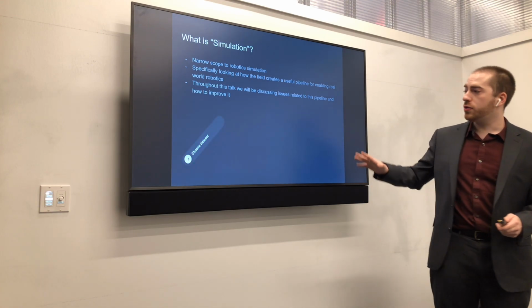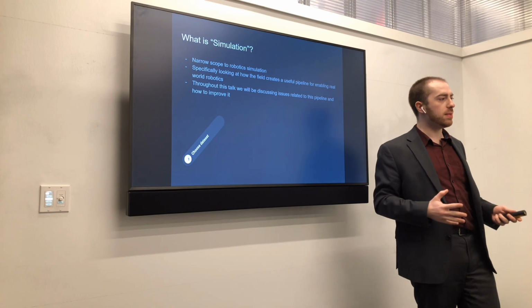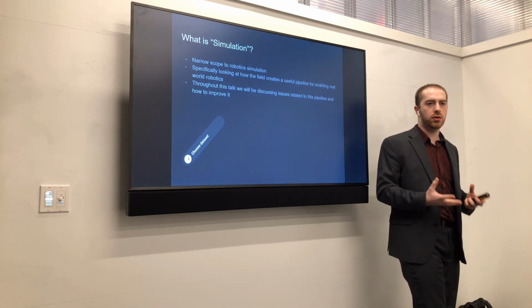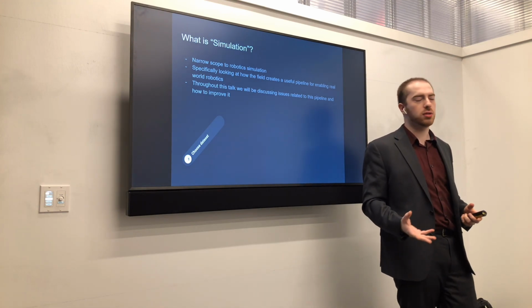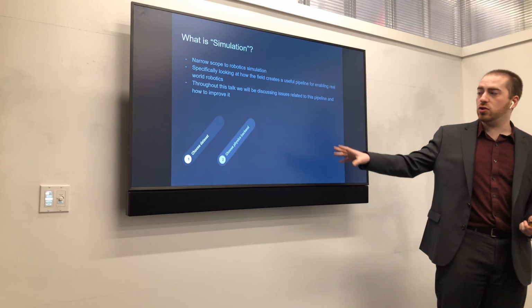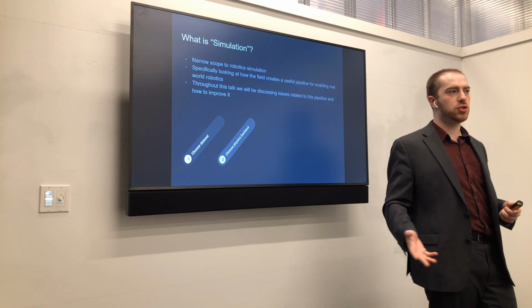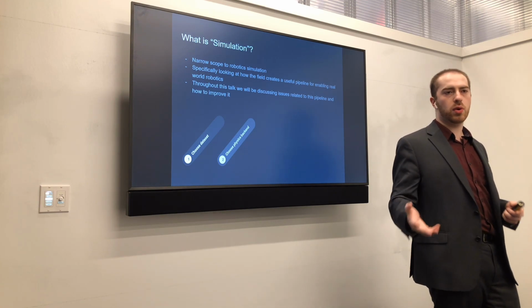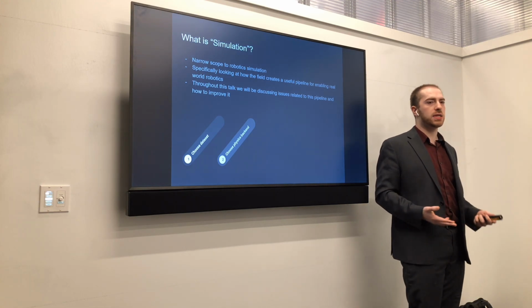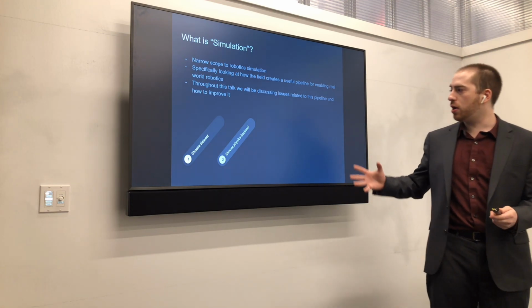general problems. So first, when you're considering a robotics sim to real problem, you always want to choose your dataset. What is the ground truth data that you're going to use for training an agent, for verifying that your application works correctly? Then you choose a physics backend that supports the particular problem you're trying to solve, whether this is MuJoCo, whether this is Habitat Sim, whether this is AirSim if you're doing drone research, or even just video games like Atari. These are the general backends that you'll be considering for the problem you're solving.